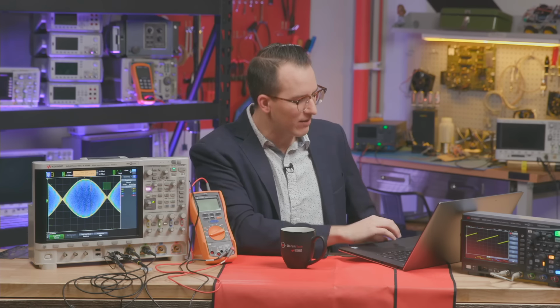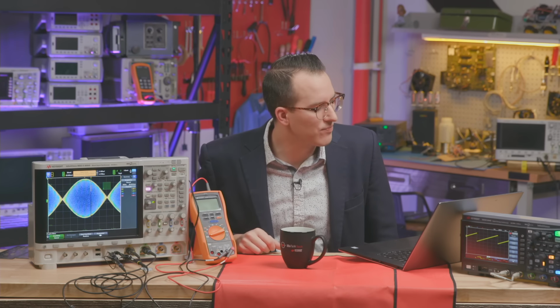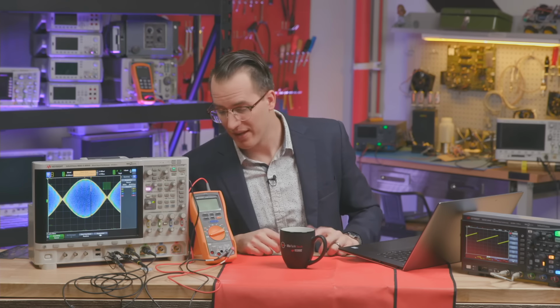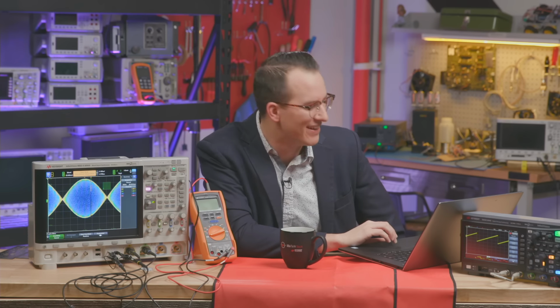Can the oscilloscope read resistance? That's a good question. Oscilloscopes don't really have a resistance measurement capability like a DMM does. But one of the things you can do is use a function generator in your scope. The 6000X has a function generator, and pretty much all the Infiniivision scopes have a function generator option. You can run a known voltage or current across the resistor and see the current, essentially like a shunt resistor, and measure resistance that way, do the math. But I think most people have a handheld DMM around. If you don't have a DMM and you have a scope, you'd be a winner in my book. But you should also get a handheld DMM.